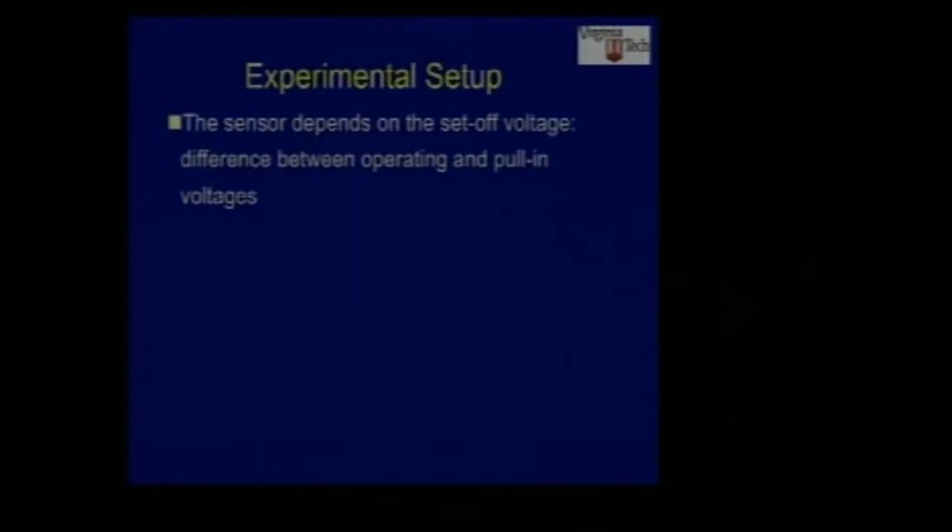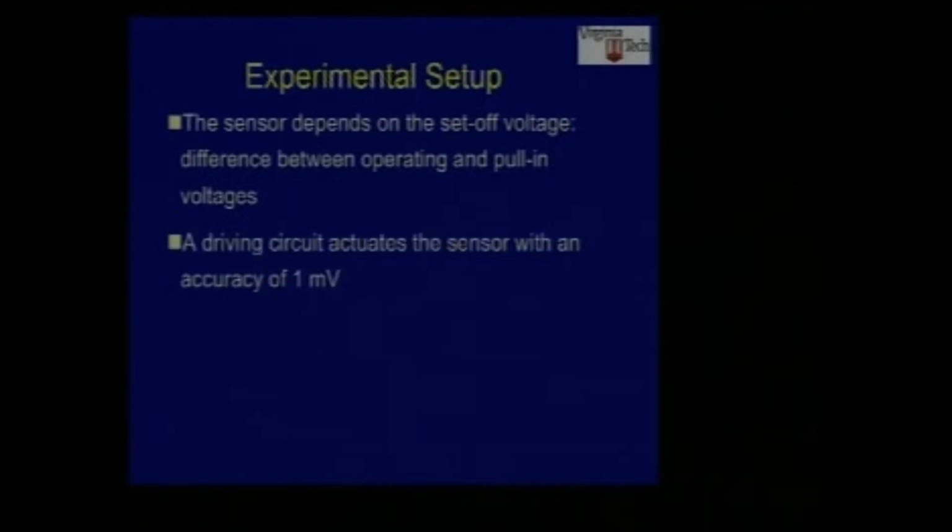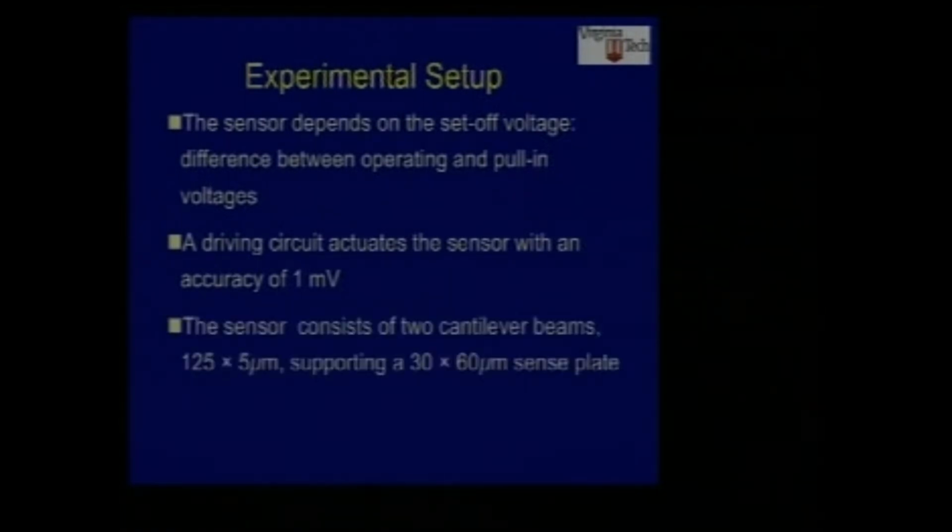They have the experimental setup, and the work is going to depend on how close you can get to pull-in and make it stable, stay there, so that when you add the mass, it itself will trigger the pull-in rather than being triggered by disturbances. So the sensitivity is going to depend on the set-off voltage, how close you are. For this one here, the driving voltage is in increments of 1 millivolt.